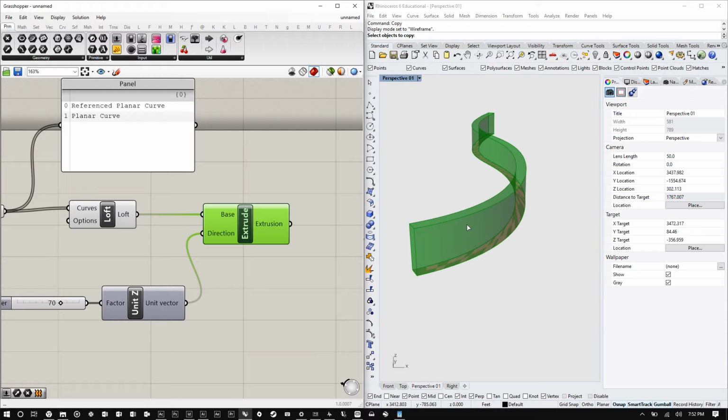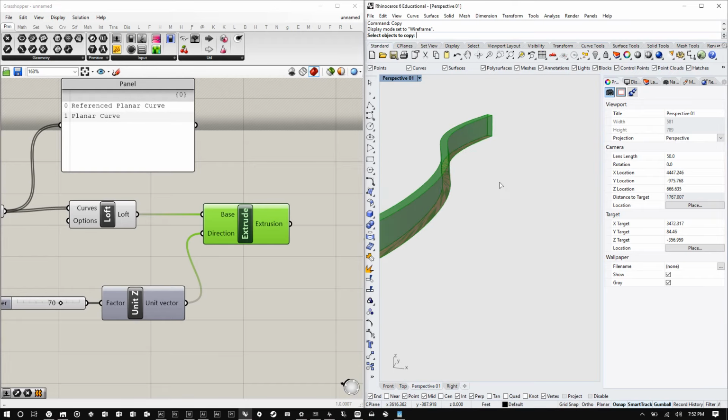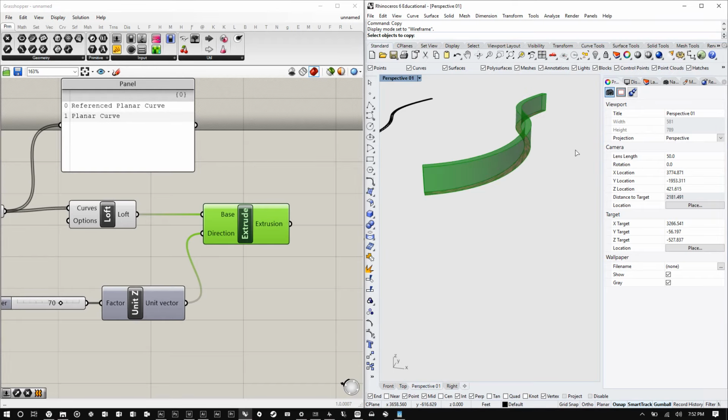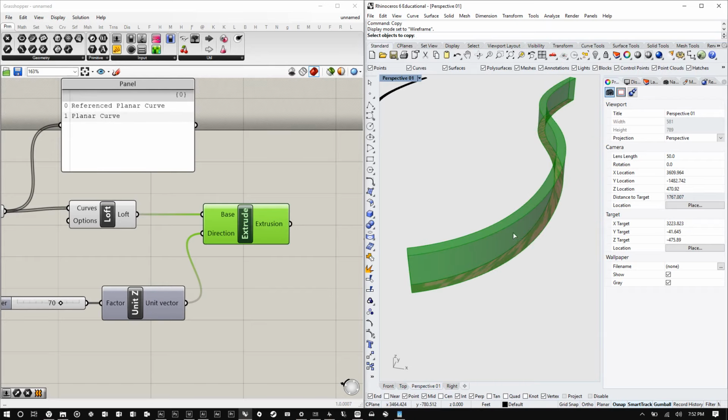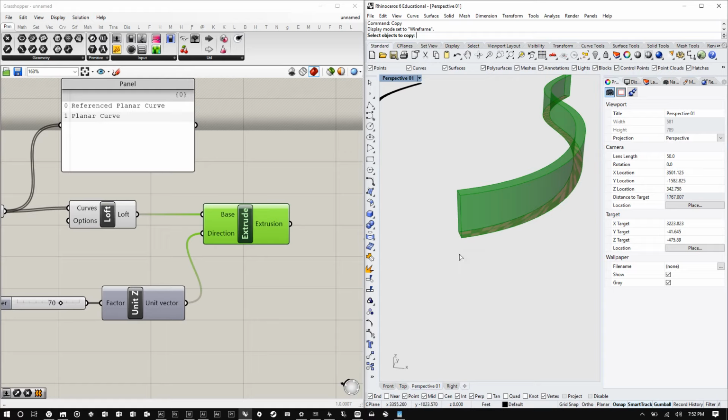Now, like I said, in Rhino and Grasshopper, you can extract information from any part of an object. So I can get a specific surface from this wall. I can get a specific curve from this wall. I can get a specific point from this wall to then do multiple or different types of edits later on. So let's say I wanted to create a pattern on this wall. Well, I could do that pattern on all the walls, but I only want to do it on one face, let's say. How do I get this face of the object?